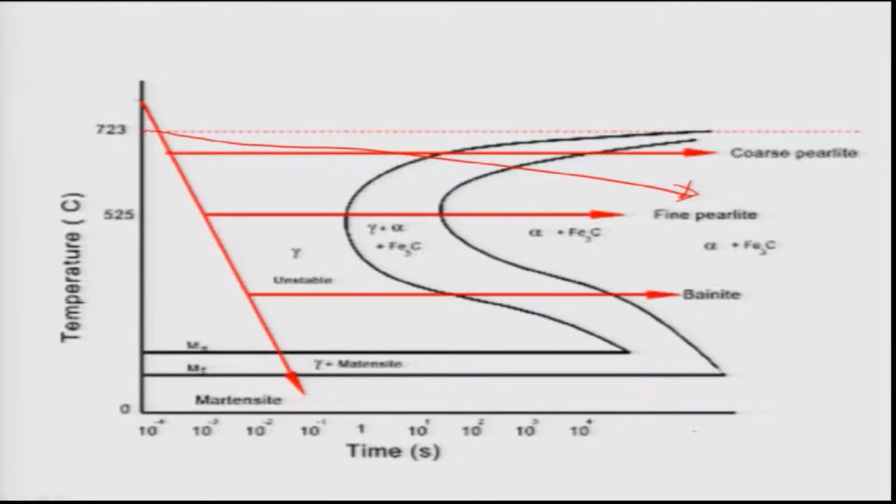So we do not gain much, because we do not want to keep it for such a long time in industry, because industry time is money. So the time at temperature cannot be so large. For bainitic transformation, alloying additions are not good, and sometimes can be costly also. But for martensite it is very good. Martensite formation can be done very easily.